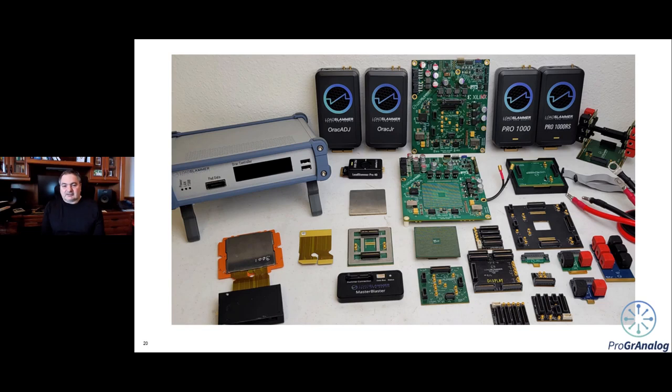Now, telemetry data isn't that fast typically with a power supply. The ADC data isn't that fast, so it's good for DC measurement and for thermal reading data back from the regulators in terms of thermal performance. And then you can set the OCP and that sort of thing. And you can read and write via the API, or there's a standalone telemetry GUI you can use.